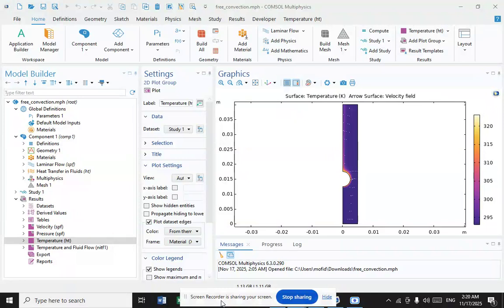To this character of fluid structure variation there corresponds the change in the coefficient of heat transfer alpha x, which in the case of developed turbulent free convection remains constant along the plate length, where the characteristics of thermal turbulence become statistically equal.